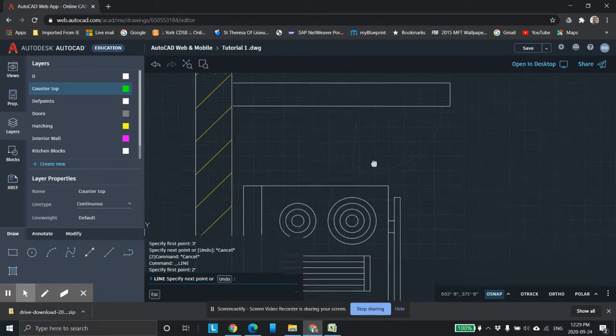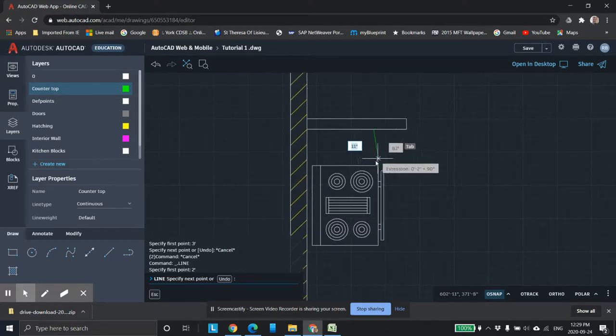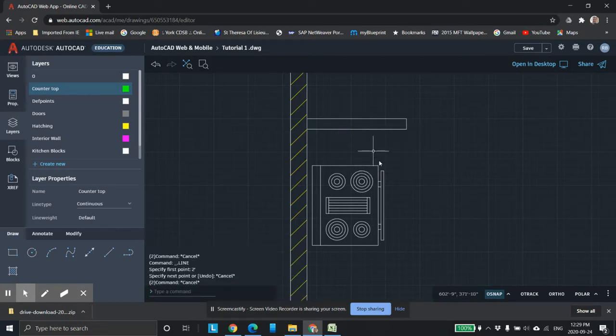Now, you don't want to just bring the countertop right up and butt it against the stove. Again, because if the stove is too wide, there's variation from stove to stove. Of 1,000 stoves, one might be a 1/4 of an inch wider or 1/4 inch narrower. So what I would highly recommend is put about an inch gap out the outside here, just for our purposes.